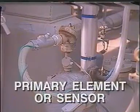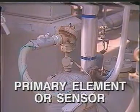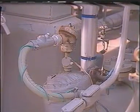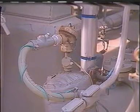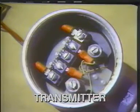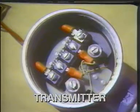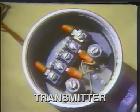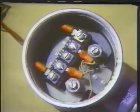We need a primary element or sensor so we can get measurement information. Here we're using a thermocouple installed in the oil flow line. We need a transmitter that will interpret information from the thermocouple and transmit it to the controller. We can use a transmitter like this one that is built into the thermocouple housing.